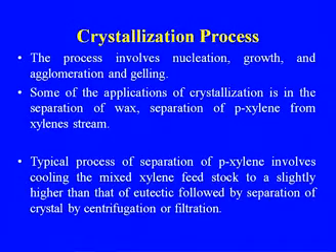Crystallization process. Earlier it was only limited to the sugar industry, where through crystallization of the sugar we separate the molasses from the sugar. But now it has come in a big way in the separation of some close boiling point components, especially the separation of paraxylene from the xylene stream. The process involves nucleation, growth and agglomeration.